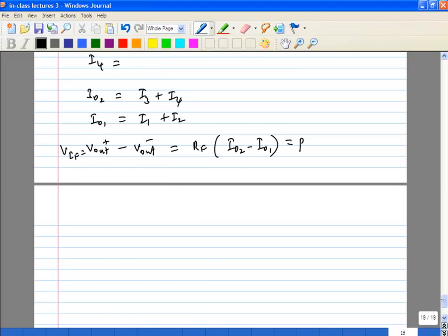And this happens to be beta times the signal VRF plus minus VRF minus, times the LO term. So this is what we wanted to achieve. We wanted to get a product of the RF and the LO terms.